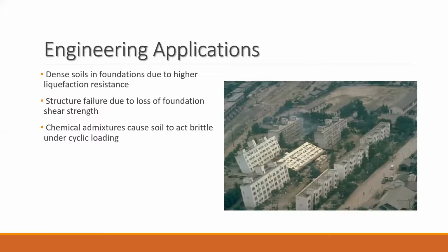Due to the effect of loading frequency on the soil behaviour, these cyclic loading tests are important in planning for earthquake actions, as different earthquakes have different frequency effects on the soil. Liquefaction resistance is an important factor to understand, as loss of shear strength of soil beneath structures can cause catastrophic building failures, such as the building failures shown here due to liquefaction after the 1964 Niigata earthquake. As discovered in the investigations, dense soils are preferable in earthquake-prone areas, as they have been found to exhibit a higher liquefaction resistance than loose soils.